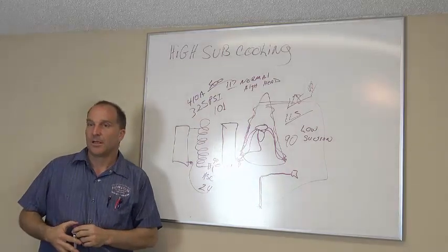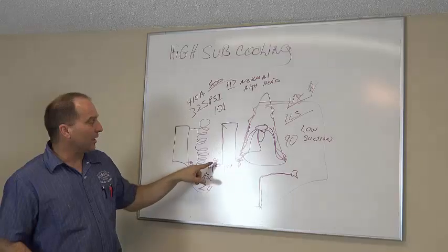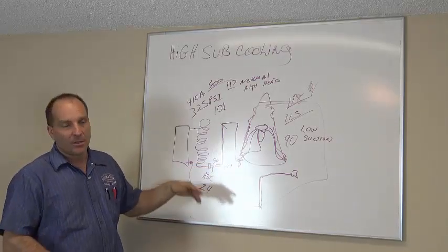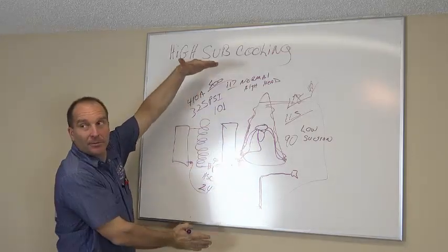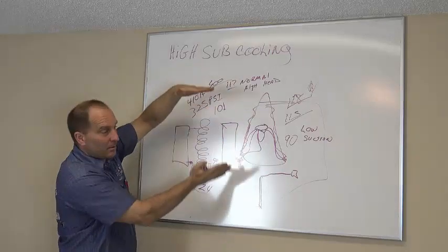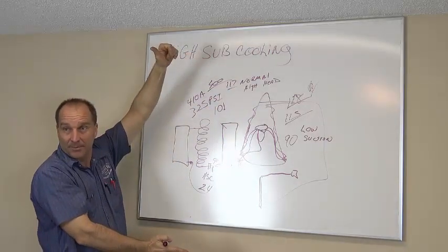Okay? So as you keep putting refrigerant in, your head pressure goes up, but your liquid line is going to get colder. It's not going to stay the same. It's going to get colder. So those two things will separate now. So your saturation temperature and your liquid line temperature separate, which means your subcooling gets higher. Make sense? Okay.